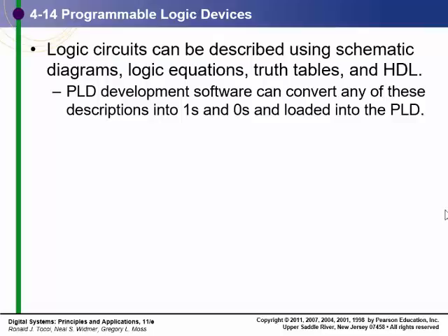This is plugged into a USB serial port, and there's a little chip in here that interfaces that. So this has the program built into it. There are also ones that don't use the USB that will talk directly to the chip and don't need any configuration cable on the board. So we can configure these things multiple ways depending on how often we want to reprogram this.